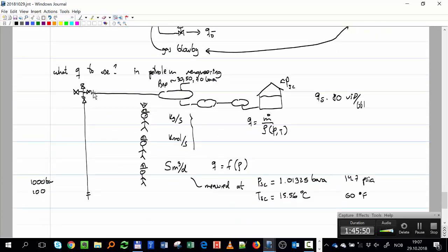Yeah, Darcy, blah, blah, blah, but I need, right? I need the velocity, okay? That's the first thing I need. The velocity is how fast the fluid goes in the pipe, and that tells me the shear it has with the walls. Okay? So, and to calculate velocity, that is Q divided by area, right?